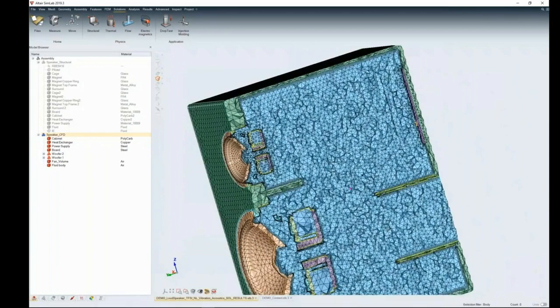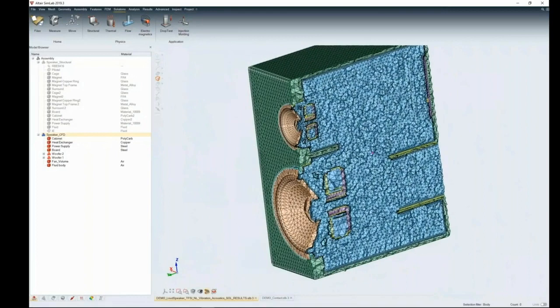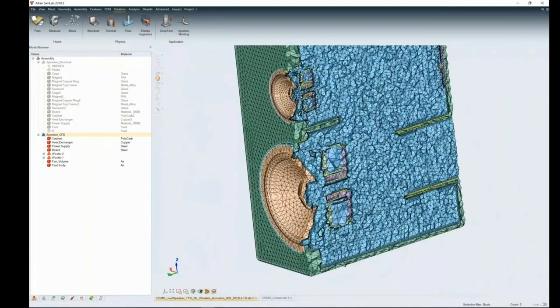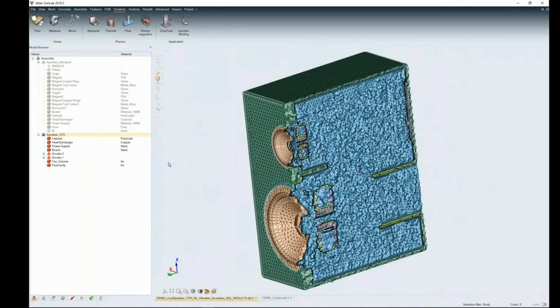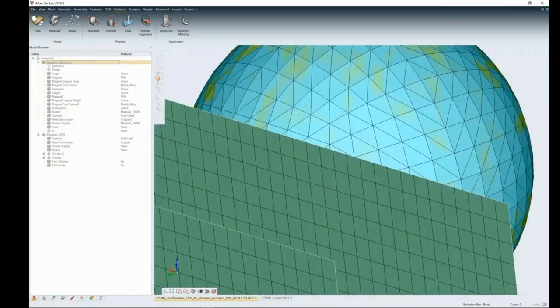Now, SimLab is not just a meshing tool for structures. It can take care of CFD meshing pretty nicely. And I think it does a great job in setting up your CFD models for your CFD simulations. Now, with saying so much in terms of the CFD, defining these inlets, outlets, making sure these boundary layers are assigned, setting up these CFD parts in terms of their materials and properties are also very nicely done. Before we get on to the material side, let's look at the structure part.